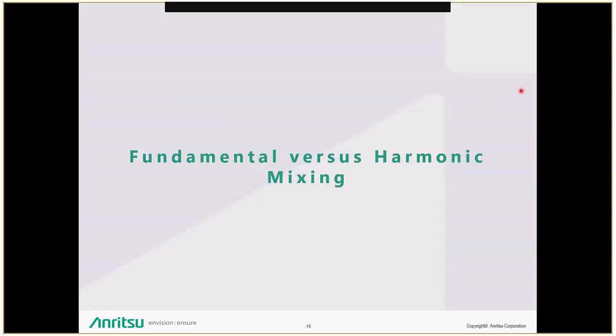Okay, now we are done with the principles of mixing. Let's go on with the differences between fundamental mixing versus harmonic mixing. Harmonic mixing has been for years the preferred technology for spectrum analyzers, mainly due to cost and also simplicity of the technology.